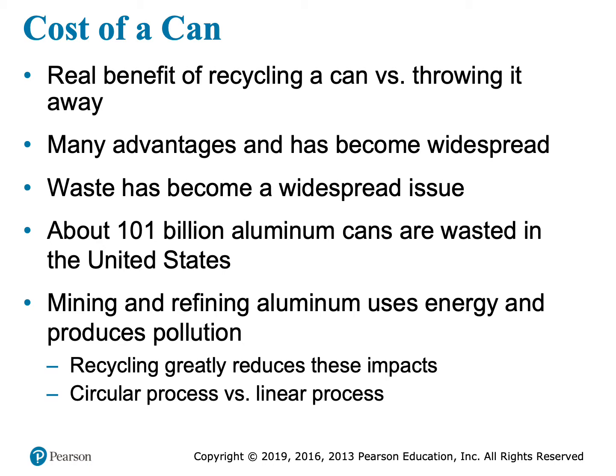In a second step, the bauxite is refined into alumina, and this process uses thousands of gallons of water and produces a toxic slurry waste called red mud. Then in a third step, the alumina is smelted to remove anything metallic, and this process uses a large quantity of electrical energy. Finally, the aluminum is heated and rolled into aluminum sheets, which can then be shipped to manufacturing plants to create cans.